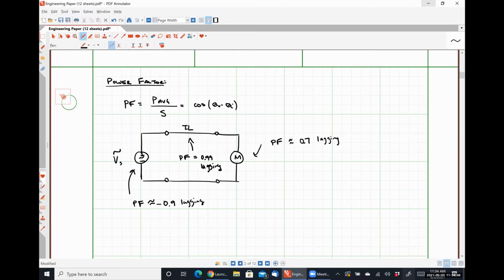You had a simple system containing a resistor and an inductor, and then you place a capacitor in parallel with that. The capacitor is there to improve the power factor of the system. But if you put too much capacitance there, you'll overshoot and wind up with a leading power factor, which means the current is leading the voltage. There's nothing particularly wrong with that, as long as the magnitude of the power factor is between 0.95 lagging and 0.95 leading, you're pretty much good.